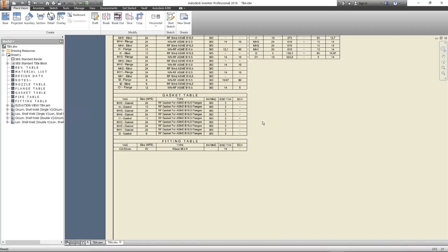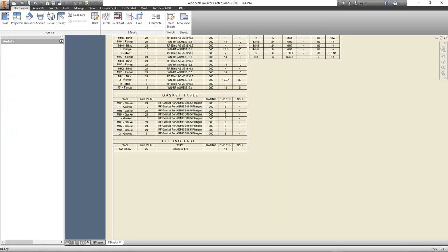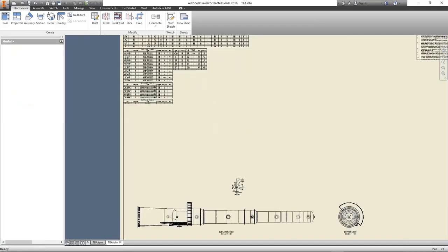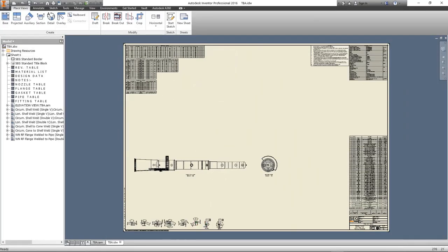And if you would like to export the nozzle loading to your drawing, you will add a load for the required nozzle, and by using this you have the ability to export the nozzle load table. Now the welding details to the drawing like this.